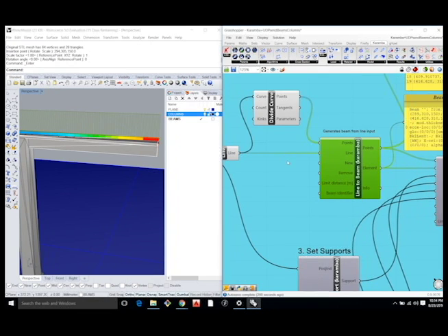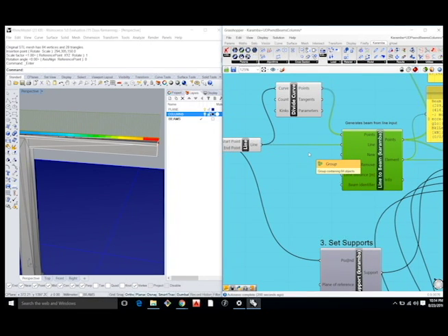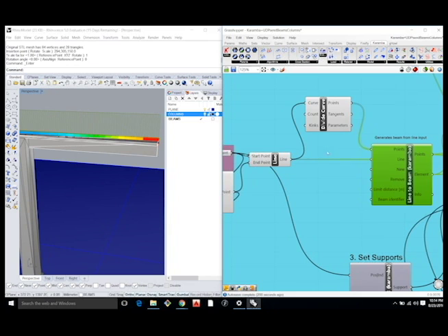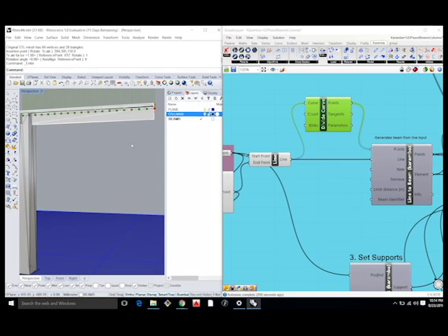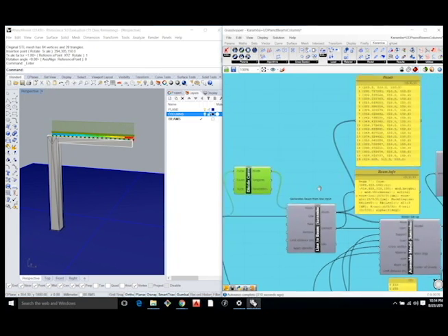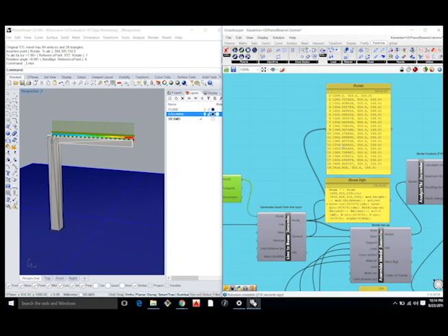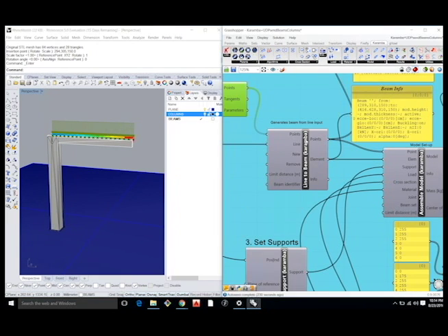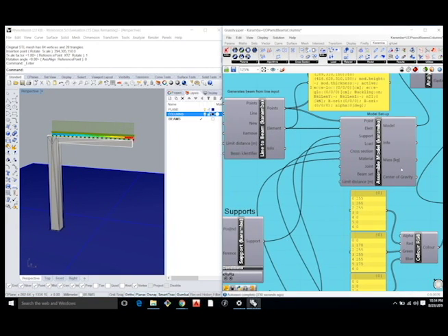So again, going back to this conversion between a design model and a construction model, what I've done here, I've divided this curve up into 20 segments. As you can see, those X markers there. The reason why I've done that is just so we eventually receive analysis at 20 incremental points as opposed to just the 2 end nodes. We've now fed a line into this line to beam, and we're ready to assemble our model.